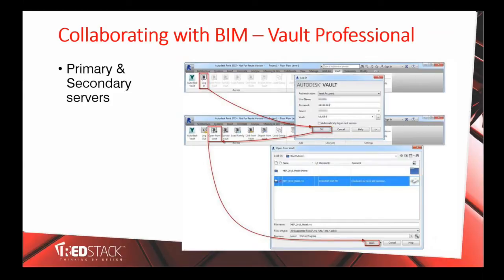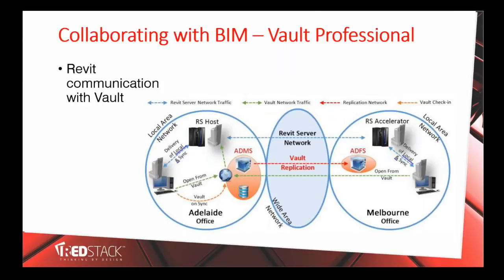And then typically you would access through the various file stores to access through the Revit Server application. So Revit communicates with the Vault, which then reaches out to the Revit Server to deliver a local file to each client via an established file mapping system. From here, Revit Server-based work sharing commences as usual.